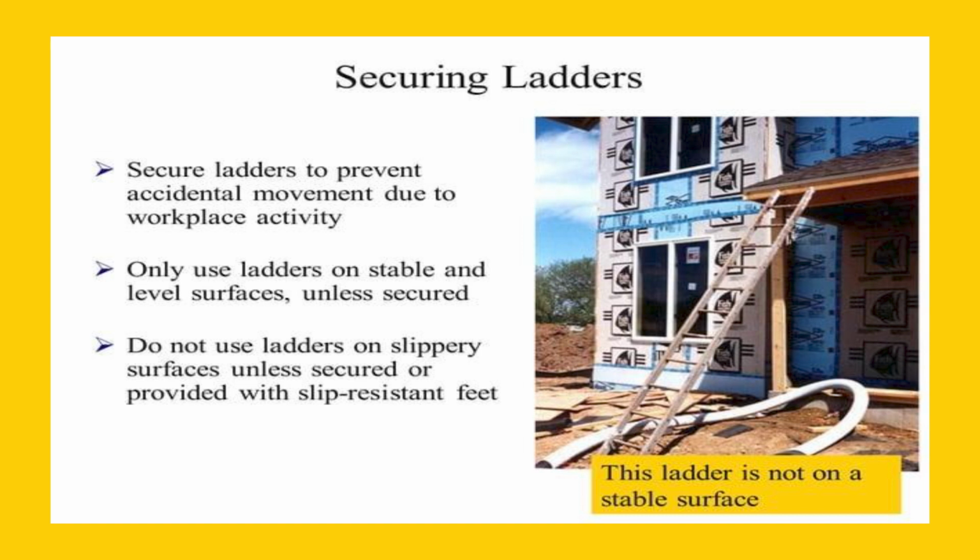Securing ladders. Secure ladders to prevent accidental movement due to workplace activity. Only use ladders on a stable and level surface unless secured. Do not use ladders on a slippery surface unless secured or provided with slip-resistant feet.